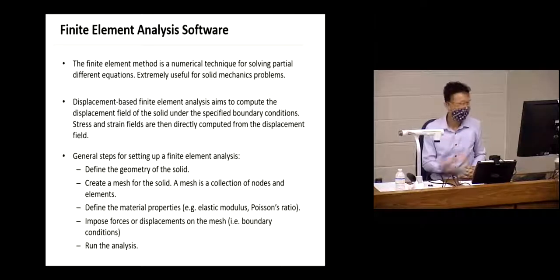Okay, and the second part, you create a mesh. That's what I just talked about, right? The mesh is just the name for a collection of elements. If we think about an element in finite element language, for example, if you look at a cube, you cut a big block into smaller cubes. That cube has nodes because that cube has 8 points. The points are called nodes, and the volume enclosed by these nodes is the element. Nodes and elements. The total of these nodes and elements becomes the mesh.